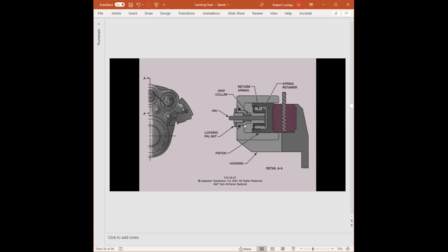Can we see that as the pads wear, the piston would have to move further and further? Thus, when the pilot applies the brakes, instead of moving the toe brake a very small amount, they have to move it continuously further and further down. Well, to prevent this from happening, many brake systems incorporate what's called an automatic adjuster.